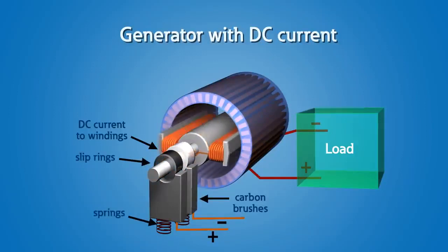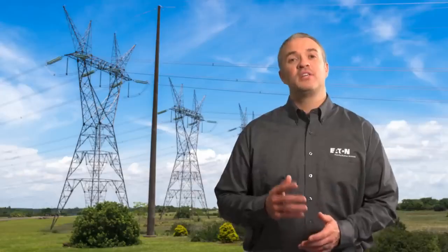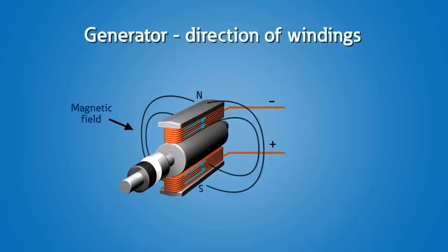Slip rings are attached to the shaft of the rotor and spin with the rotor, while brushes are stationary and connect to the end of a wire with a spring pushing on them against the slip ring, making an electrical connection. The field winding is a continuous wire that is looped around a certain number of poles that are part of the rotor core, with positive polarity connected on one end and negative on the other. North and south poles will be created depending if the coils are wrapped clockwise or counterclockwise around the poles.